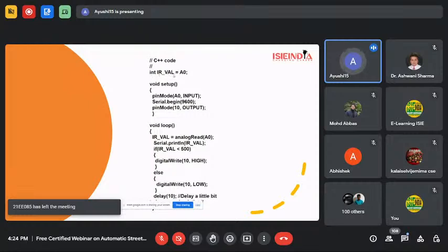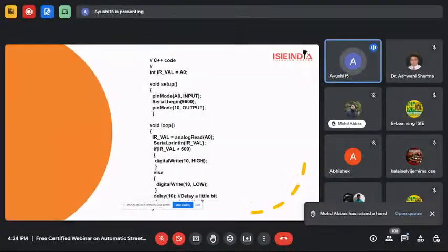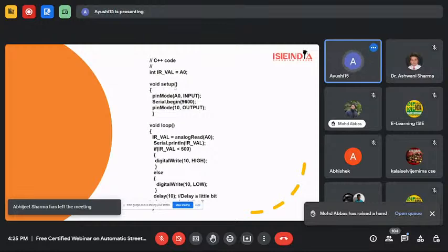Firstly, we need to initialize the variables, the void setup function, and the void loop function. The void setup is the first function to be executed in the stack, and it is executed only once. It usually contains statements that set the pin modes on the Arduino to output or input. A0 is the input pin here, which is executed in the void setup.